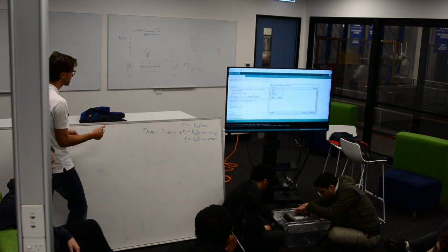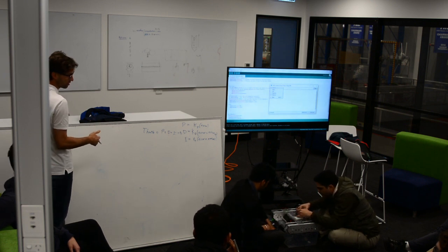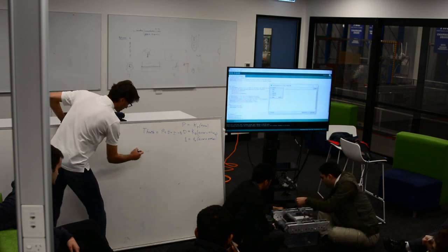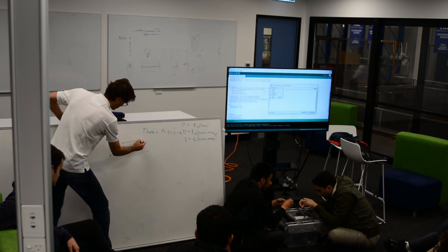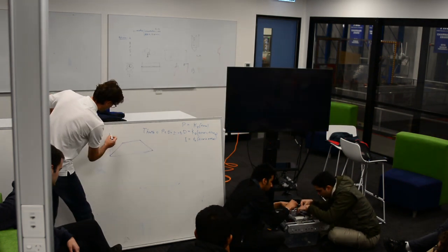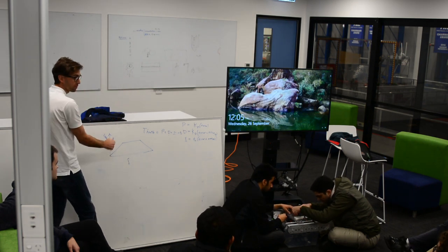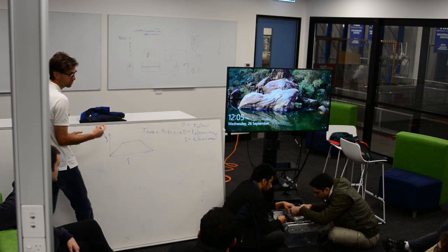So typically, on something like the CNC, whether it's the student one or the large one, it will move the spindle from where you are to where you want to go. It looks like this. This is what's called a trapezoidal move, where this is velocity and this is time, and this is trying to go from position A to position B. So it ramps the velocity, holds the velocity, decelerates. That's called a trapezoidal move profile.